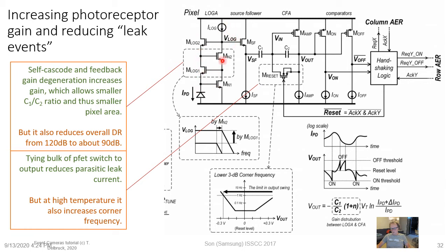And the higher the gain of this amplifier here, when you pull this down, if this gain is higher, it makes this gate swing more, which makes it look like the source conductance is higher here, which speeds up the pixel because it reduces the pole here at the front end. Basically, higher conductance here coupled with capacitance here decreases the time constant and makes the pixel go faster if you want it to. Of course, you can always low-pass filter it by reducing this supply current here and also in the source follower if you want to limit the bandwidth for limiting noise.